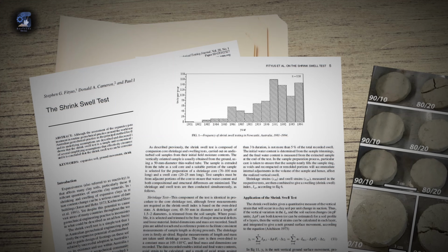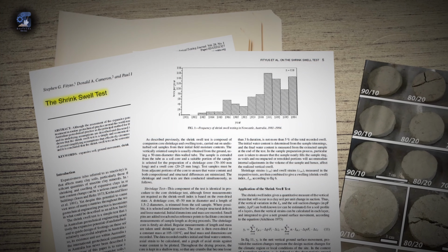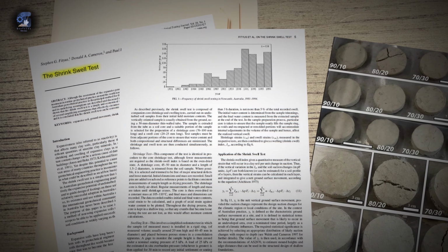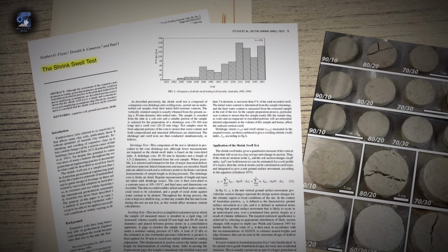So, how do engineers determine the extent of soil reactivity and design appropriate foundations? Remember, in my introduction, I mentioned collecting soil samples for lab testing. If the site is underlain by clay materials, a shrink swell test is conducted to check the sensitivity of the soil. The initial moisture content of the soil sample is measured. Then the sample is split into two.